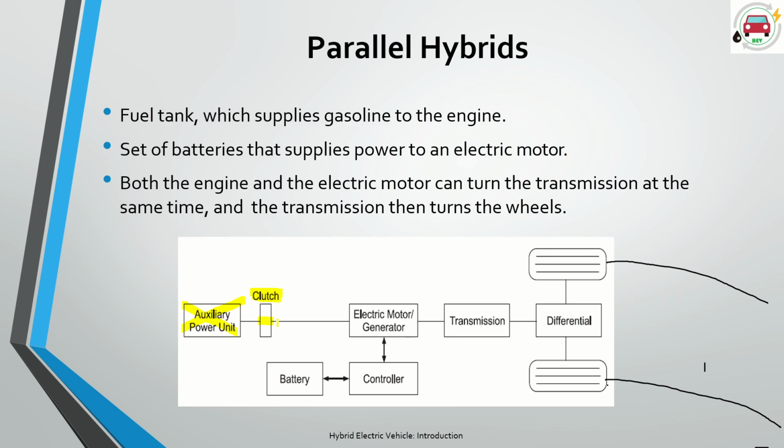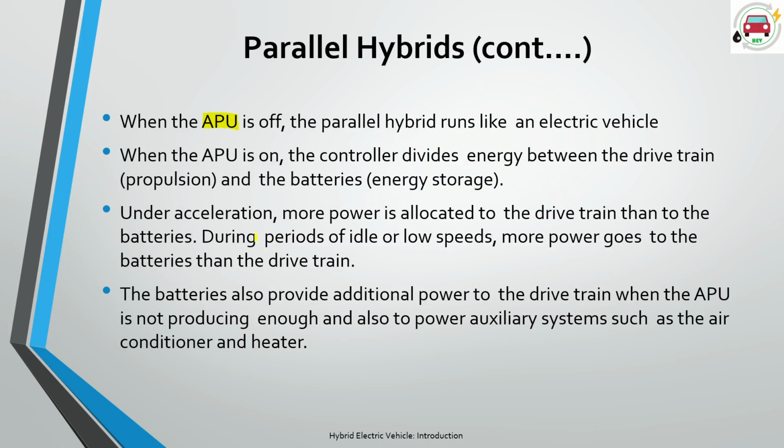We disengage this clutch, right? So the connection between these two will be gone. Okay, so only the electric motor will run the transmission and differential. Then this will be purely an electric vehicle, not a hybrid. Okay, so this can be possible in the parallel hybrids.